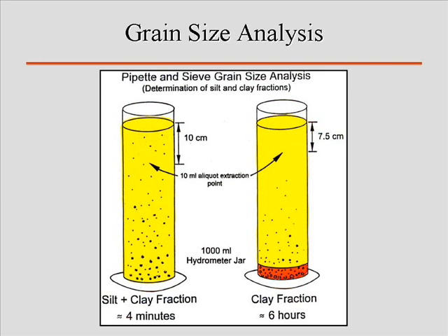Part of the grain size process is to take your sample and break up all the particles in their smallest disposition. They're going to be in a water base already. So instead of actually dumping the sediment in the top, what we do is we put the sediment in the columns and then agitate it. We use a simple plunger device. Basically, you keep the column moving, and then when you get to a certain time when you want to start timing things, you stop. Now right away, you should see what an issue is with that.